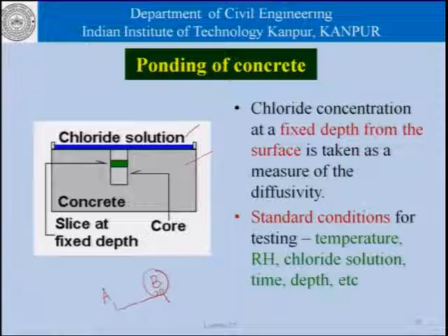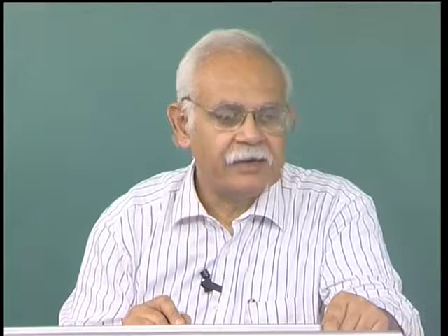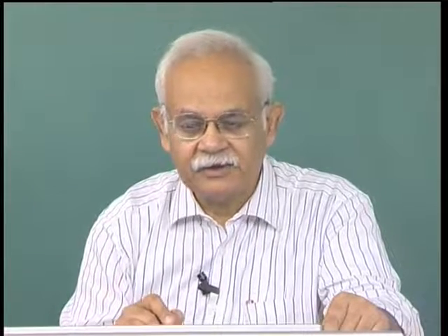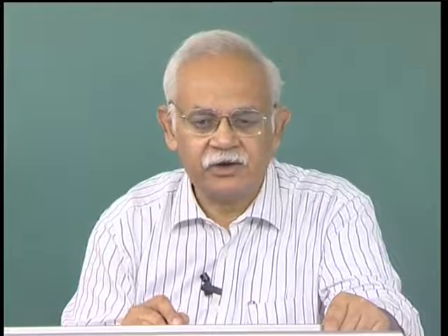What this method does is not give you a quantitative number in terms of the diffusion coefficient, but helps us rank different concretes in the order of chloride diffusivity.